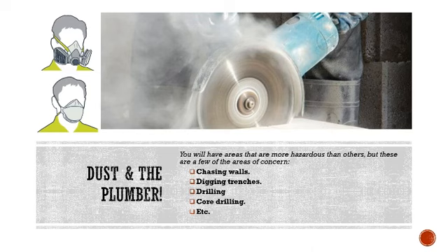But when we're going through concrete, asbestos, or perhaps working on a site where there's silica dust, all those are finer, smaller particles, perhaps even working with cement at certain times, you will notice that the top respirator is probably going to be more ideal for that working environment, especially for the extended period of time that you might be working. Again, refer to your risk assessment to tell you which is the best type of PPE.